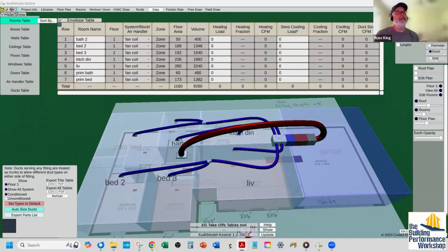Exactly. And honestly, that comes from having run 2 mechanical engineering departments, and I was blessed that almost every single design we did, we had field people who would go out and test those houses. When I could, like if I were doing the first houses in a subdivision, I would go out with them and test them. But to get that feedback, to draw a set of plans and say, I want 98 CFM of air to come out of this register, and then they build that house 20 times, and every time they test it, 98 is the design target, and the measured is 112 or 115. It's really close, but a little bit better than what we designed to.